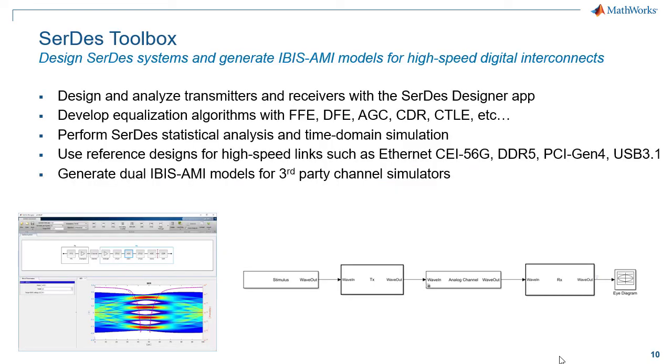As a conclusion, I would like to summarize how SerDes Toolbox covers all aspects of SerDes design and verification. From the SerDes Designer app, you can start the design exploration and rapidly iterate through your specifications, including also impairments such as jitter and crosstalk. In Simulink, you can verify the SerDes performance in the time domain and customize the model to include proprietary algorithms. At last, you can generate standard compliant dual IBIS-AMI models for the SerDes verification and integration into third-party channel simulators.